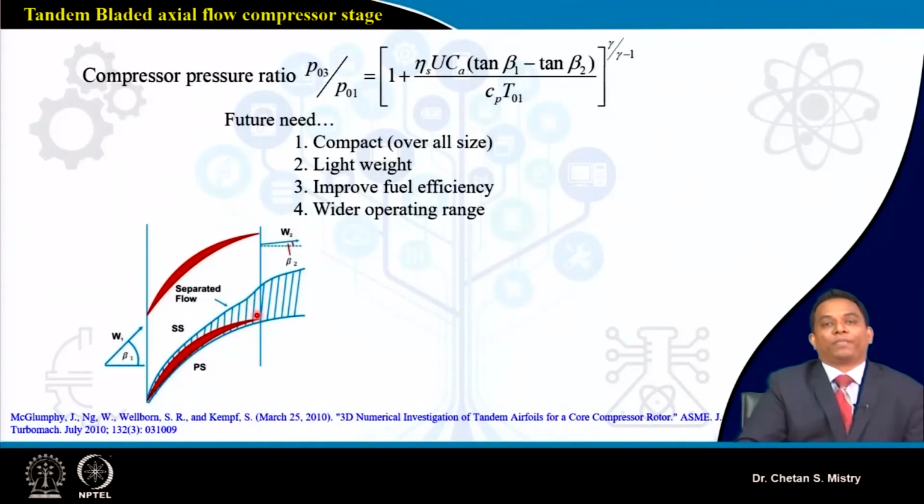That is defined as stalling of the aerofoil; for a compressor, we can say it's a stall of my blade. If this stall continues for some time, it converts into surge, and that will lead to catastrophic failure of your engine. That's the reason, again let me tell you, the compressor is the heart of the engine. If it is not working fine, your engine will not work, and that is very important.